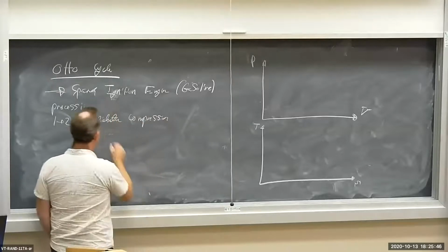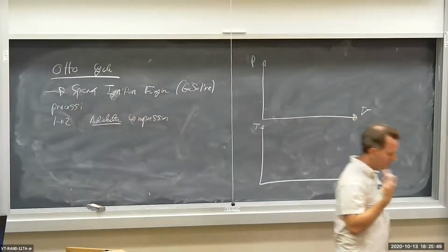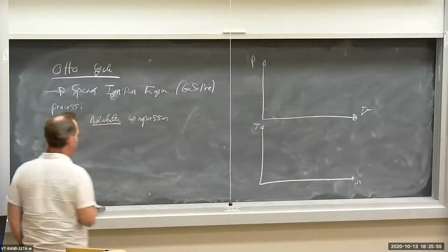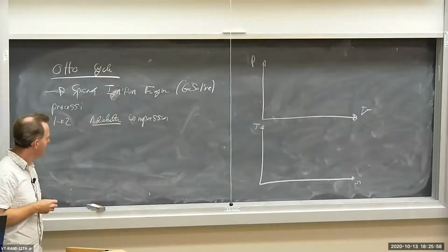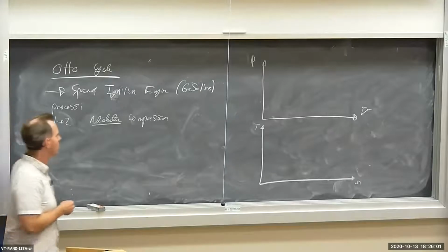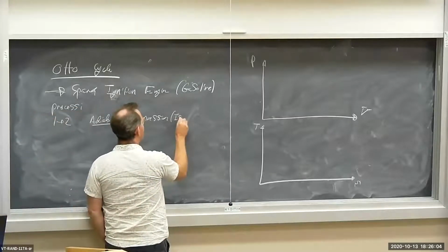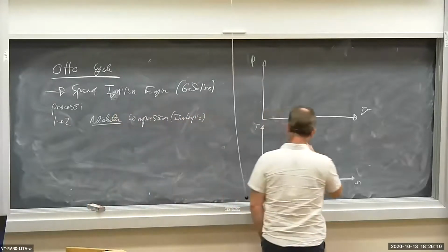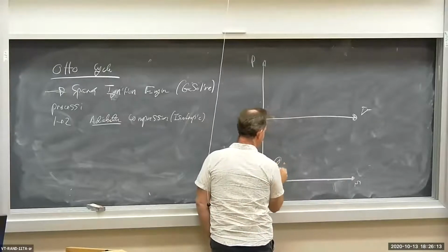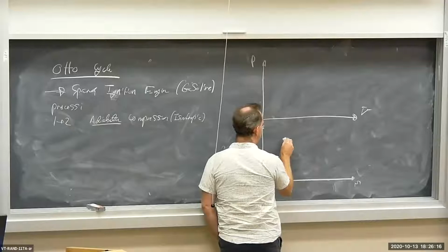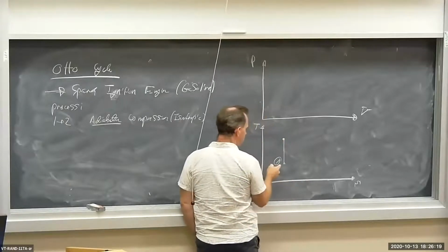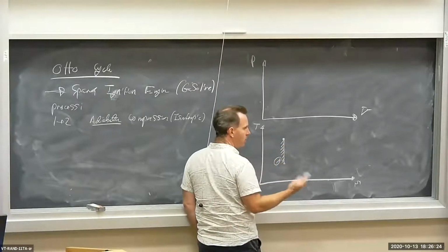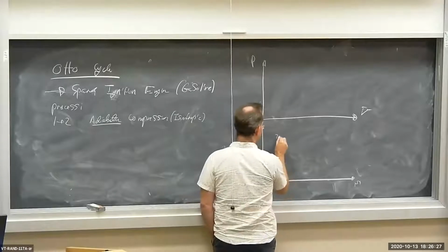By the way, if it's adiabatic, you apply the entropy balance, assuming an air standard cycle, of course, with no irreversibilities within the piston cylinder device, within the system. If it's adiabatic, it also means that it's isentropic. So it's also isentropic compression. So here's state 1 right here, up to state 2, isentropic compression. Temperature starts initially at T1 and goes up to T2. We're compressing, volume is declining, so temperature goes up. So here's state 2.